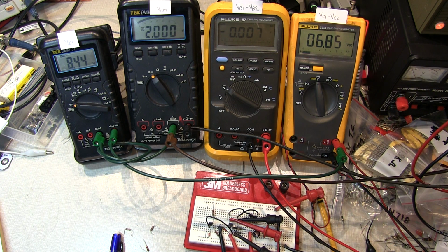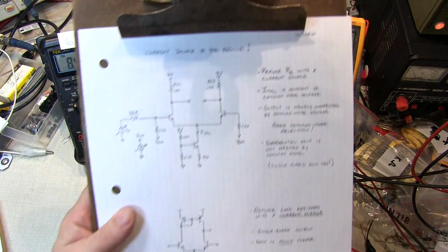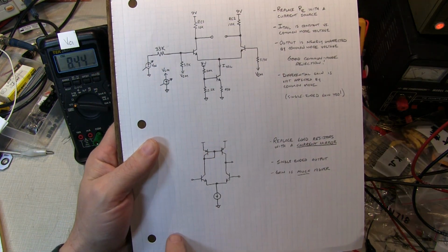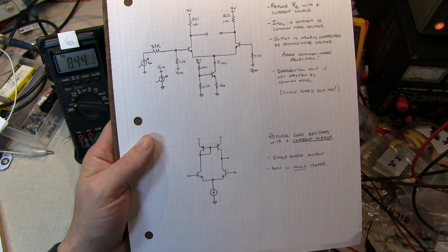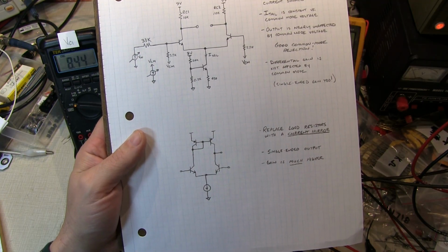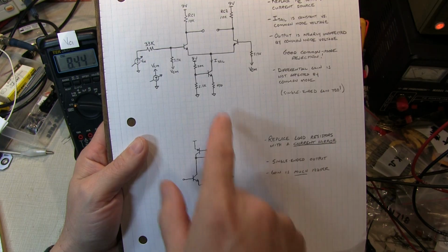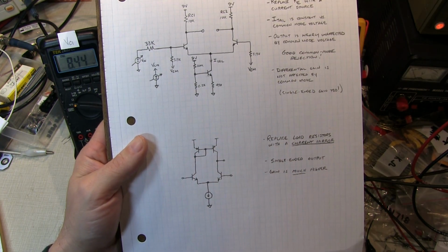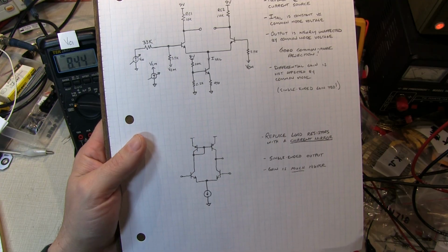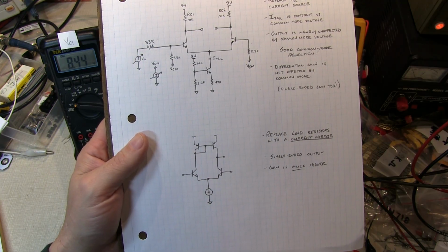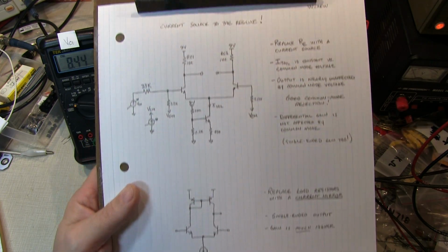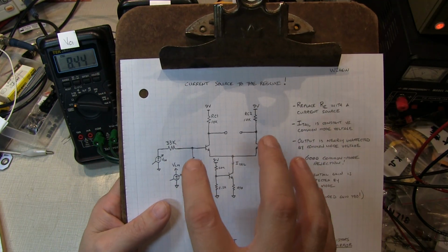So take a look at this circuit structure, with the current source here, and a current source here using mirrors as the load. It's called an active load. Start looking through the data sheets of the op amps you like using, and you'll start to see these structures built in there. You may start to recognize why some of these structures are used and how they form the basics of how the op amp works.